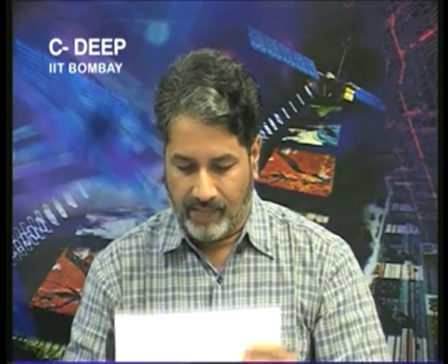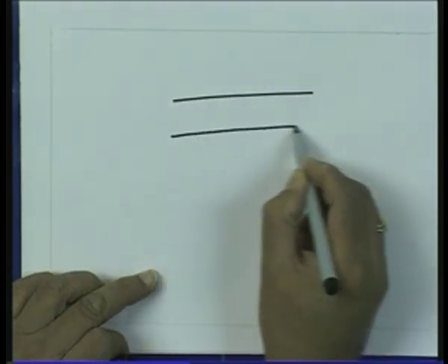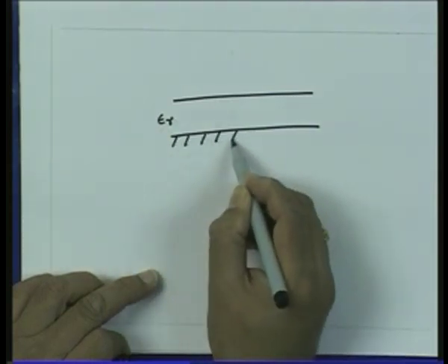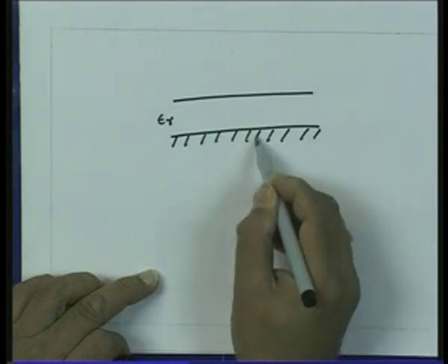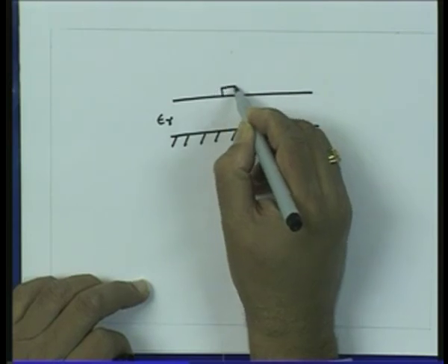The third structure which you see commonly in practice is what is called the microstrip line structure, and this structure normally is realized at microwave frequencies for making circuits. Also, whenever we have printed circuit board configurations, you have this kind of transmission line. So, this structure is: you have a dielectric slab with dielectric constant epsilon r, which is plated with a conductor on one side, and there is a strip of metal on the other side.